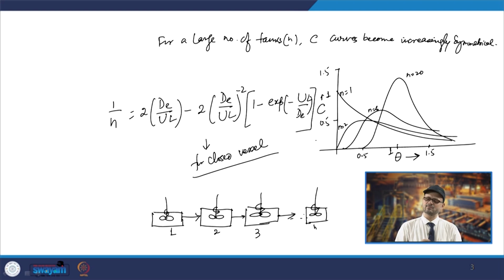That is indicative of the other things also, like you have different regions. Here you have a completely well mixed zone starting, whereas if you go to the other regions, there is no dispersion. So, you have a plug component as well as a mixed component. Those things can be analyzed using these curves, and they have certain meaning. As you move, you see that it is getting delayed. So, the plug part is getting apparent here, whereas in this part the plug part is not seen, because here well mixed flow is more prominent. That way you can analyze the curves in different manners.